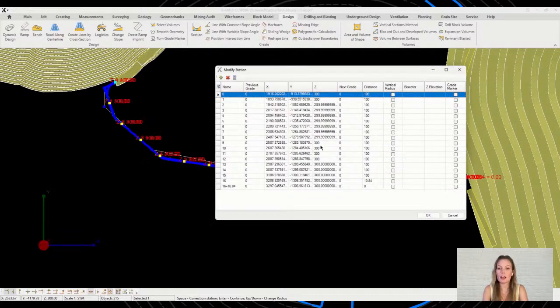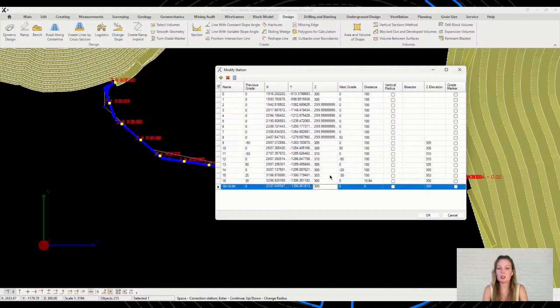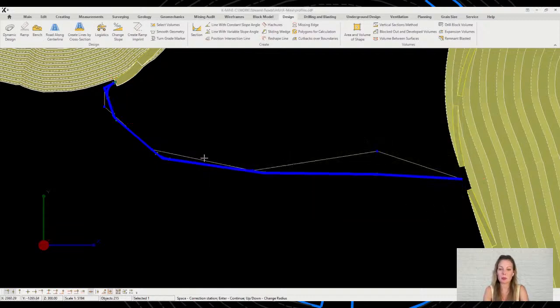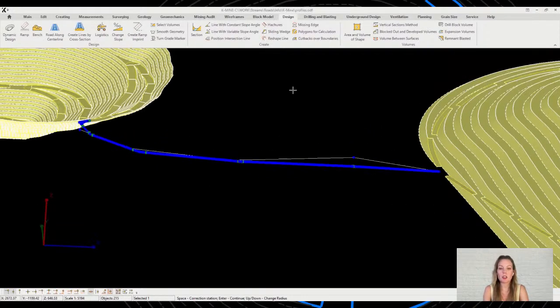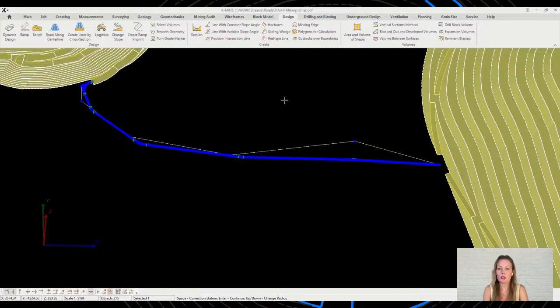In order to adapt our road in elevations, you need to use the Modify Stations menu, which is called up in the mode of dynamically changing the road by pressing the space button. Here you can change the elevation of each point, thereby tracking their compliance with the landscape. The changes are dynamic and all dependent parameters will be recalculated automatically, which makes it possible to control the construction at all stages.